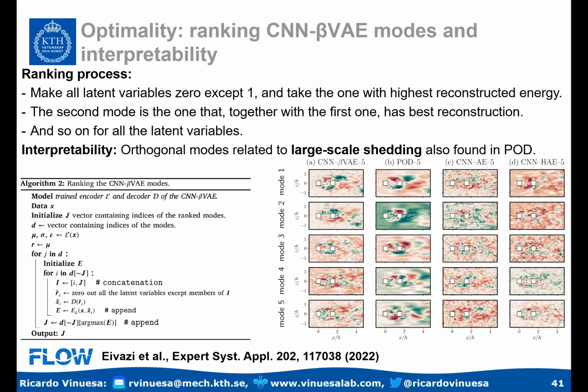And that's interesting because that's basically allowing me to combine many of those POD modes into only one, and get similar features, but where I need to use this for predictive temporal predictions as a reduced order model, then I only need to worry about 5 modes rather than 500. So in principle, I believe that autoencoders, in particular these beta variation autoencoders, are really giving me a lot of potential to build reduced order models in turbulence, no? When we really have this very broad range of scales, and then POD doesn't really help so much.